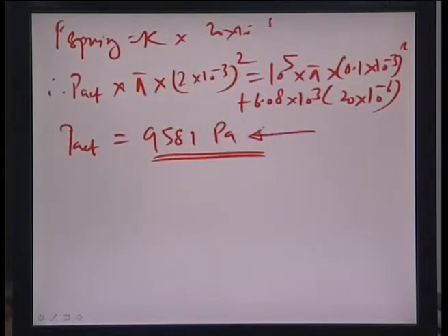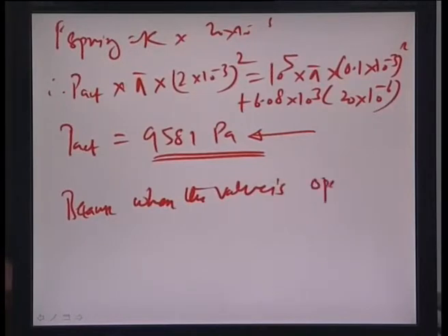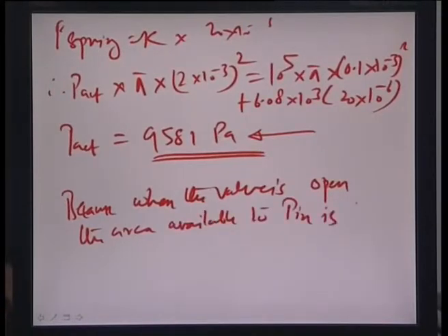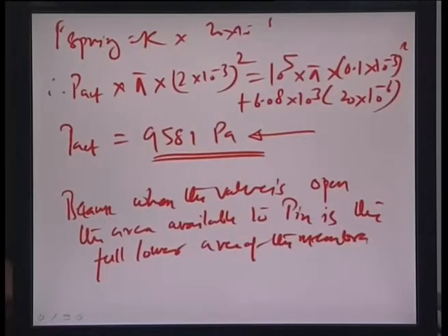So, why is that so again? Because when the valve is open, the area of membrane, or the area available to the inlet pressure, is the full lower area of the membrane, okay.